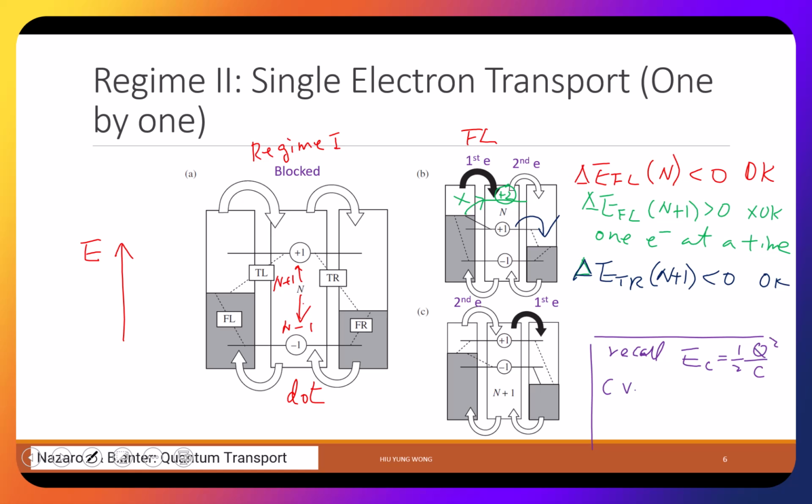You make C very small, or T very small, then you can have this single electron effect. Because when C is small, the separation of these levels is large, then I really can do it one by one. Or make T very small, even if your separation is not large, I do not have this Fermi tail that gives thermionic emission. If it is absolute zero, I only have electrons up to here, right? If it is 300 degrees, you might have some tail.